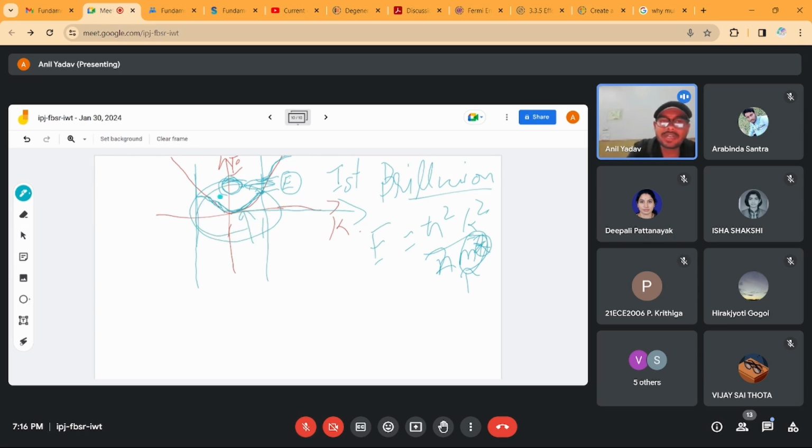The effective mass of the electron captures the curvature of the conduction band, and the effective mass of the hole, m_h star we call it, or m_e star for the electron, captures the curvature of the valence band of the E-K diagram. Valence we cannot call it a band, because band is a different thing. Valence diagram, whatever.